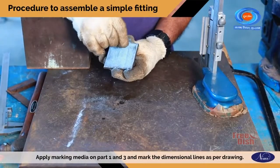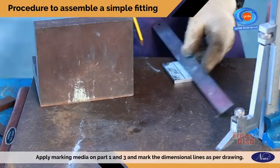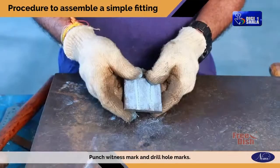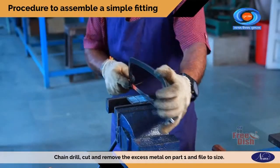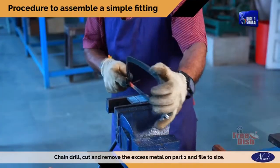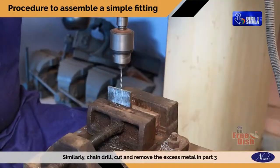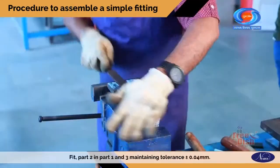Apply marking media on part 1 and 3 and mark the dimensional lines as per drawing. Punch witness mark and drill hole marks. Chain drill, cut and remove the excess metal on part 1 and file to size. Similarly, chain drill, cut and remove the excess metal in part 3 and file to size and shape.